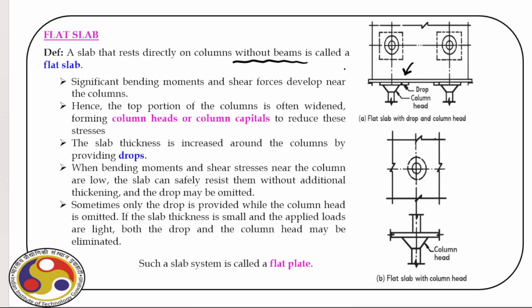We have to take care of that. Now, as you can see here, one of the common practices is to widen this column head. As you can see here, it is widened. So if the column is like this, widen it, and then there is a drop panel. So we have a drop panel here, and then on top of the drop panel, we have this slab sitting.